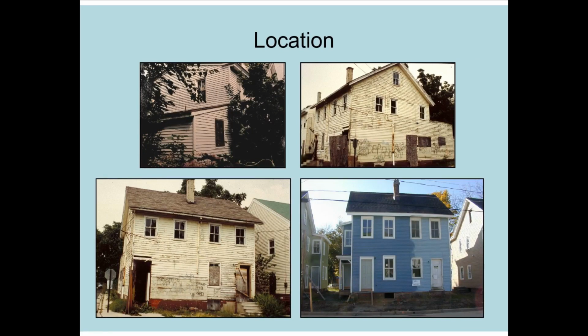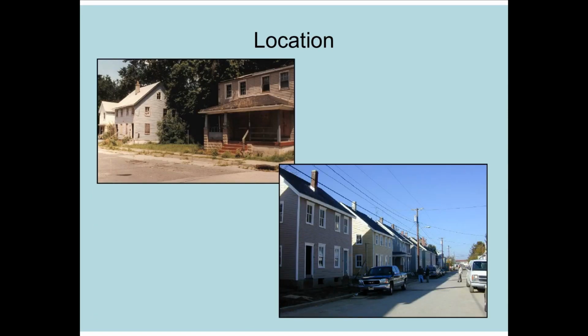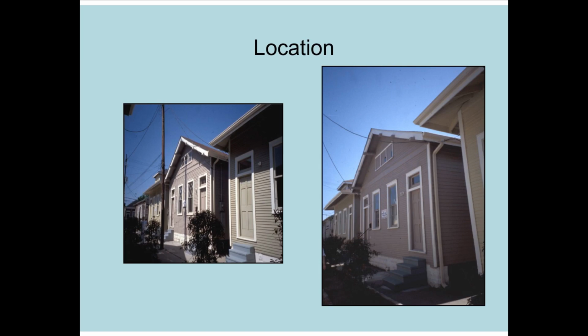Materials on the rear elevation or side elevations with limited visibility due to the proximity of neighboring buildings may be of secondary importance to the building's character. Here is an appropriate use of fiber cement siding on the side and rear elevations only.